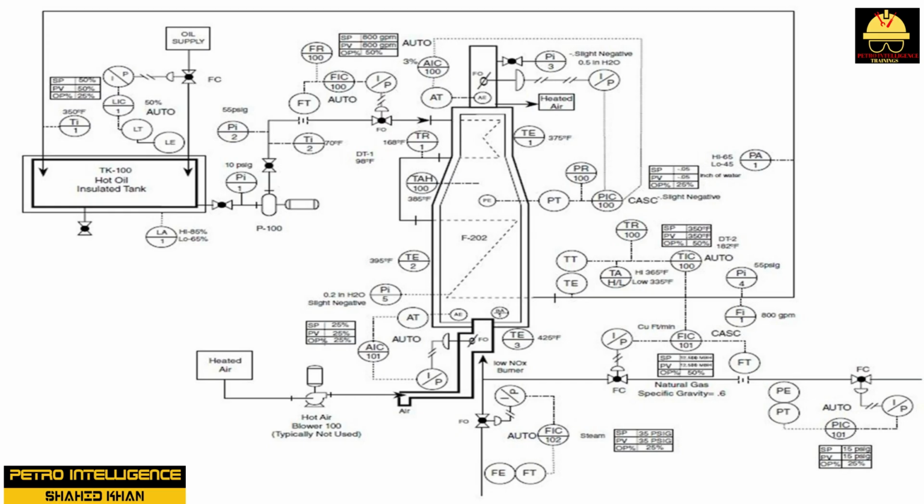Simple startup procedure for furnace system. 1. Notify your supervisor and all concerned about startup: downstream process technicians, I&E, engineering, maintenance, etc. 2. Ensure all safety hazards are secured: trash, locks, old permits, etc. 3. Check equipment and instrumentation: stroke control valves 0 to 100%, check lineups, etc.